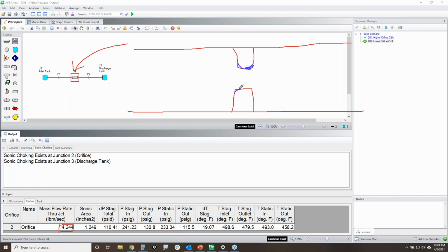Maybe this is what can help increase your flow area a little bit, because if you're making those more rounded, you might have a little bit bigger of a space for that flow area than when it was sharp edged. So that might be something you can do to help increase your CDA value to get more flow rate even while remaining sonically choked.